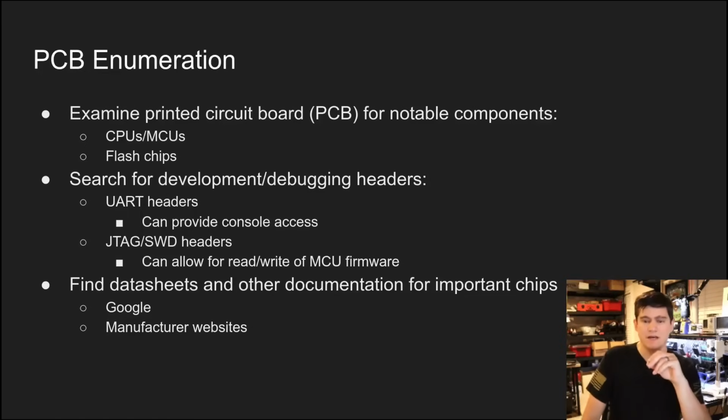And oftentimes, I'll make a point that I don't have here in my slides. You want to get the device into a functional state with it outside of the shell. Now, depending on the device, that can have a whole bunch of complications. Potentially, you want to power the device with a bench power supply like I have over here instead of the traditional power supply for a whole bunch of reasons that might be complicated. But you usually want the device to be exposed when it's running so you can do a lot of this testing that we're talking about here in this slide.